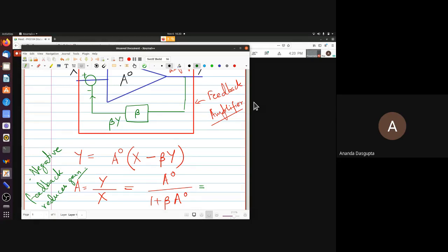But the problem with the transistor is that the gain will depend strongly on the transistor's parameters like the beta, or at least HFE, HIE and all these values. And these are actually rather fickle. They tend to change with various conditions. The beta might change because of temperature, might change because the operating voltage has changed, because the bias has shifted for some reason.